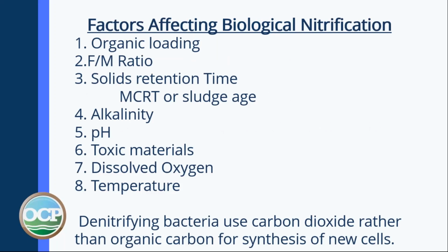Factors affecting biological nitrification: your organic loading, food to microorganism ratio, your solids retention time, MCRT or sludge age, alkalinity, pH, toxic materials, dissolved oxygen, and of course, temperature. Denitrifying bacteria use carbon dioxide rather than organic carbon for the synthesis of new cells.